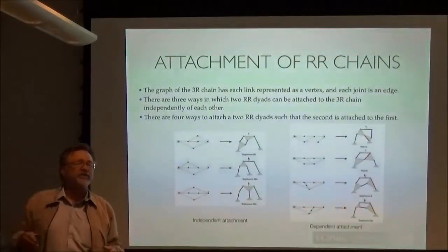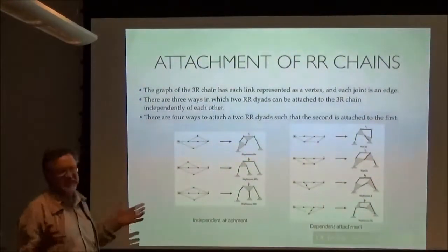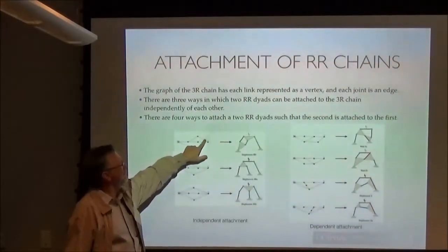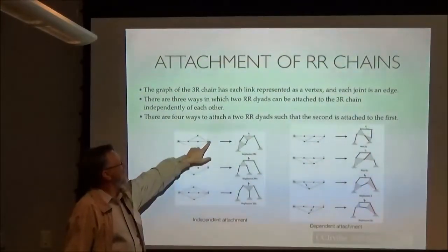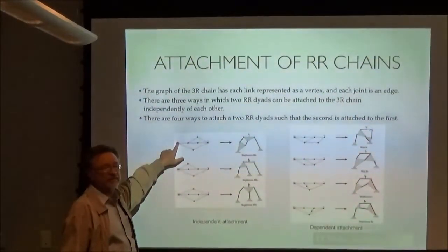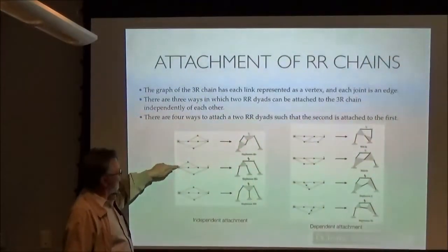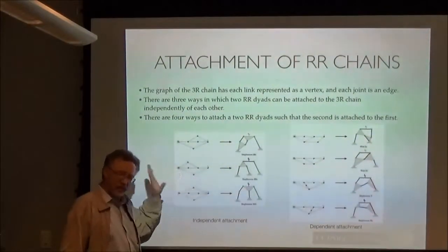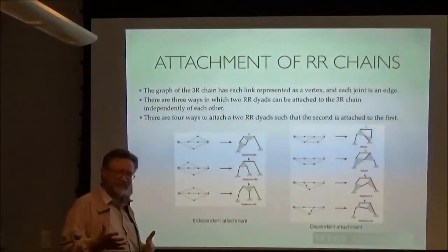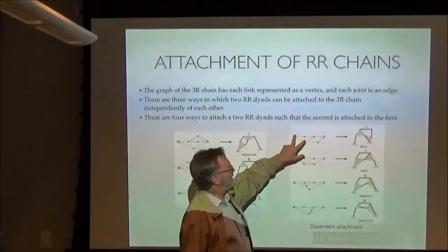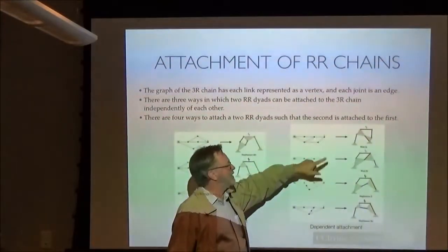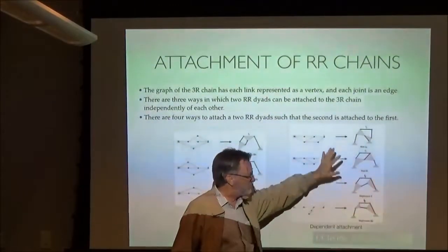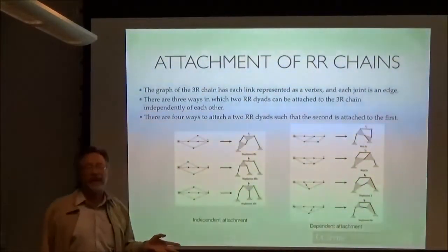I'm going to walk you through some just interesting things. Once you've decided to do that, I'm going to take a serial chain and I'm going to constrain it. Well, I can constrain the end effector to the first link, and then I can also constrain the end effector to the ground link. Oh, wait, I can also go the ground link to the second link and the ground link to the end effector. Oh, wait, I can also do, you know what I mean? You start realizing I've got alternatives. And not only that, if I connect the ground link to the second link, I could also connect the end effector to that link. So I wind up going through these combinatorics and I wind up getting all these different mechanisms.